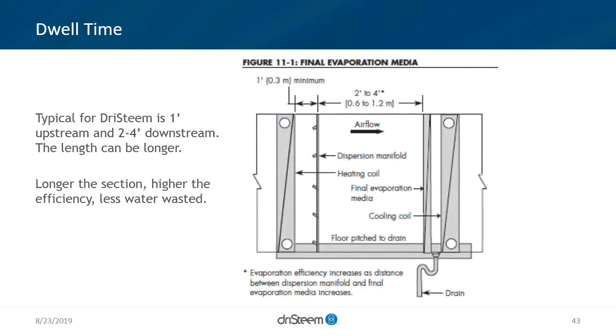So dwell time, one of the things is, and I heard this the other day, kind of the expectation was 6 to 8 feet required for HPA. And really what I commented on that is we typically see 2 to 4 feet. And what you guys and gals out there designing these systems for air handlers, it's really how do I maximize the efficiency, but minimize footprint and run up against those constraints of cost of air handler and that tunnel, essentially.